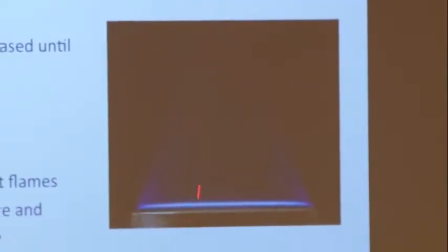So what people usually do is they measure the temperature profile, and in a simulation you would impose the temperature profile. You just say, I use the temperature profile from the experiment and just compute the species, for example. Okay, so this is very often used here to study flame structure, to do measurements maybe for species.